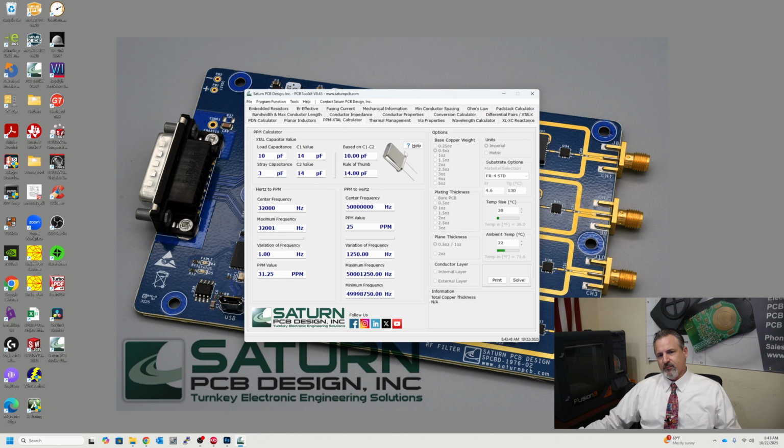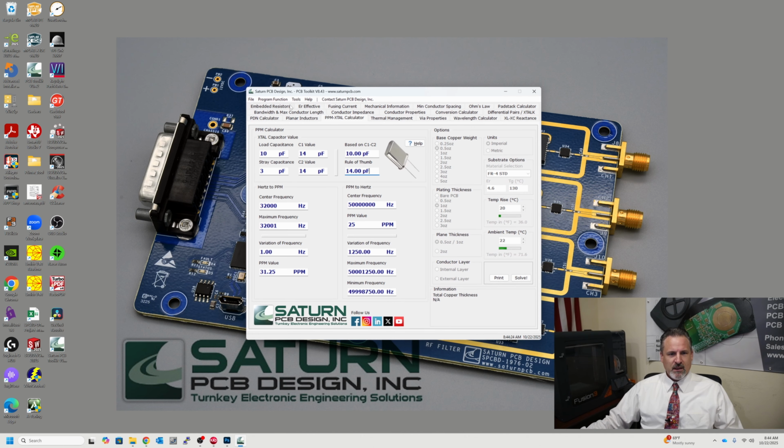I really didn't think people wanted to export the crystal capacitor. I'm sorry, the crystal calculator. It's actually pretty useful if you understand how to use it. You want to read the article here. It helps you configure those capacitor values to get the crystal to start up. And also you can actually change the frequency of a crystal a little bit by its capacitors. But anyway, so I've already set up some exports for re-importing, but I'll go through it again here real quick.